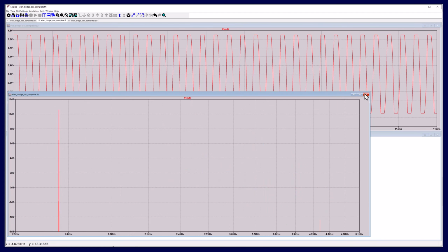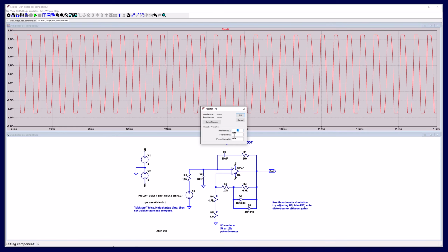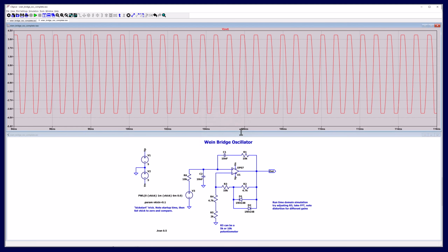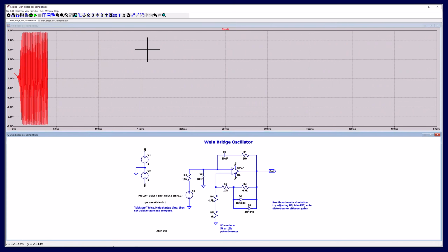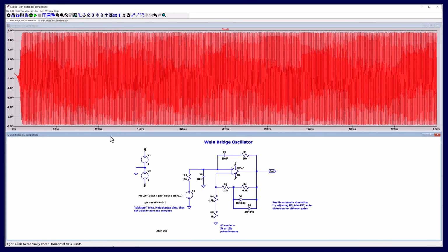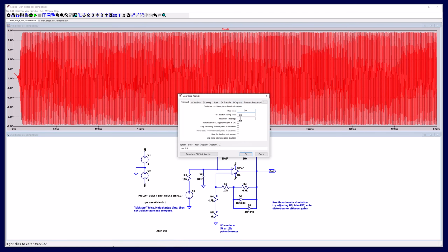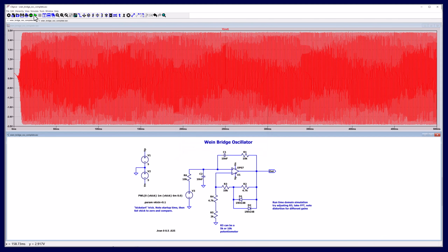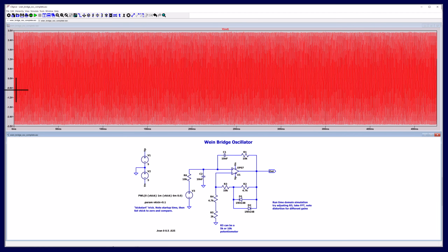Okay, so let's get a little bit better here. So we'll go and again, we know that 2K, oh, sorry, that was 1.8 ohms. Okay, well, that actually accentuates our experiment, so that's good. So let's go back to 2K, which we know oscillates. And now let's take the FFT. Oh, I also want to take this initial startup out of my FFT. So the way I'm going to do that is I'm going to start saving time at, let's call it 25 milliseconds, 0.025. Okay, great. So now when I start up, my FFT is only going to consider the waveform after my startup transient has died out.